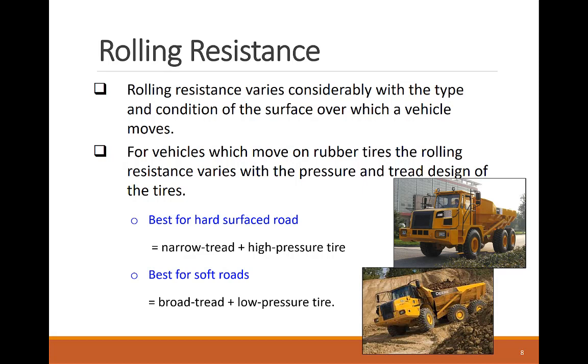We can see this pattern in natural history, where camels have been used for centuries to transport goods in deserts. Camels' feet are wide so they can walk on sand more easily. Their huge feet help them walk on the sand without sinking into it. The same applies to heavy equipment and loose natural soil. Using low pressure tires increases the tire flexing and distributes the load over a wider tire-soil interaction area. The broad tread helps in locking into the soil, especially when it is loose or very muddy.